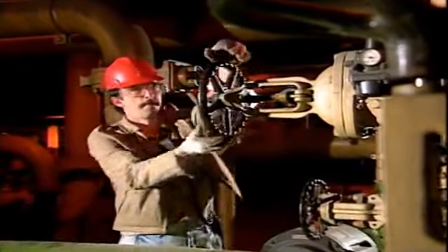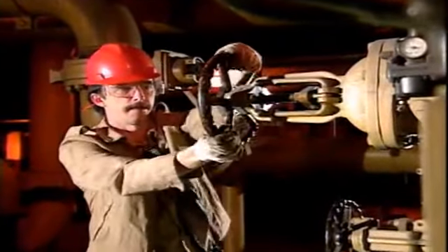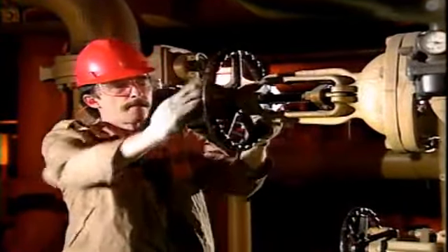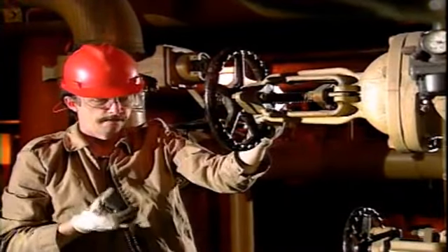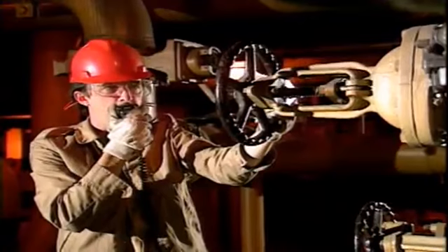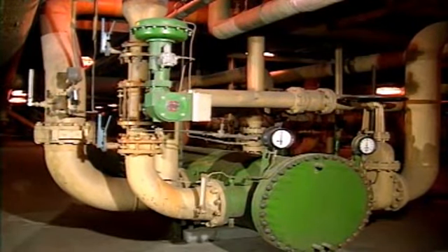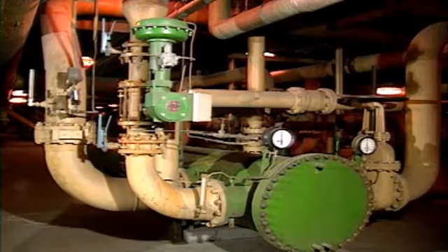When either a manual operator on an actuator or a bypass line around an actuator is used, it will probably be necessary to maintain communications with the control room to ensure that the proper flow rates are maintained in the process. Since there are so many different possible configurations that actuators and control valves can be arranged in, you should check your company's procedures before operating any actuator manually or on the bypass.